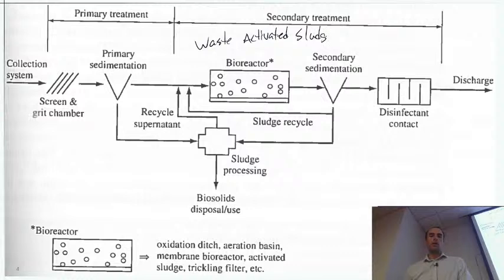It's a sludgy mixture because we've got a lot of bacteria growing and whatever other waste is in there. And this is allowing aerobic bacteria a great opportunity to munch on bacteria food, which could be waste grease we dumped down the drain, could be just all the organics from our excrement and all the waste products. Whatever is in there that could be biodegraded is being consumed and used as food for the bacteria.